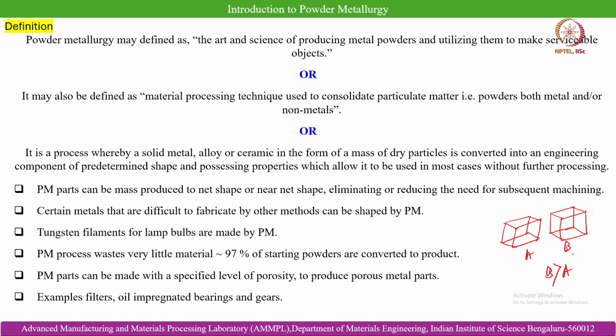These parts can otherwise be developed by micro machining techniques, but that poses significant challenges in terms of economic viability, the requirement of special purpose machine tools, and the experience of the operator needed for precision micro machining operations. All those difficulties can be dealt with effectively when we work with powder metallurgy processes.